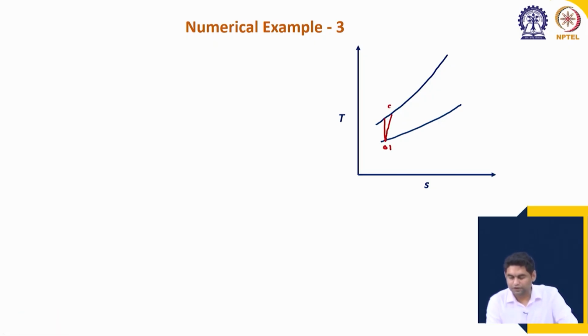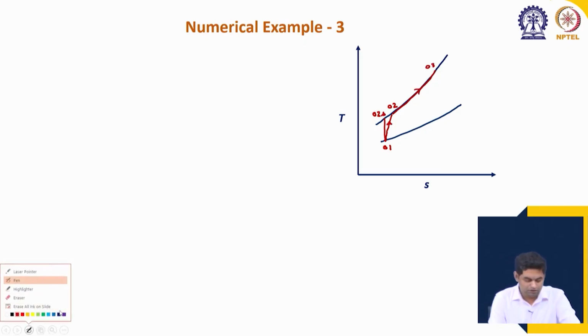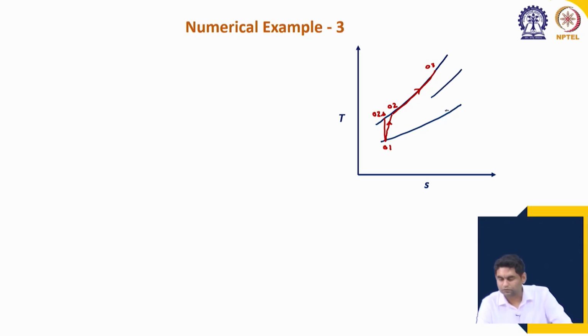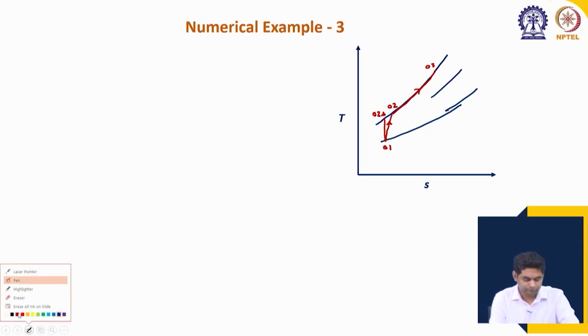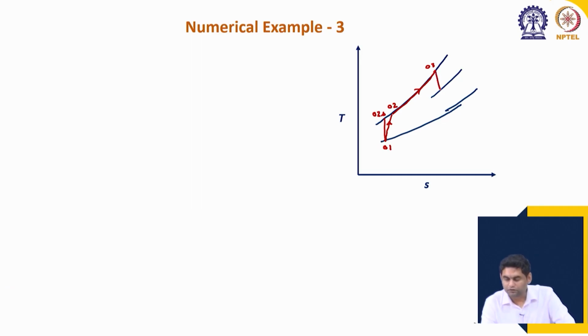So, again you should also practice how to draw these diagrams quickly, because it is very much essential. 01 to 02 compression, 02 to 03 combustion, then 03 to 04 high pressure turbine expansion, 04 to 05 low pressure or free turbine expansion. Okay. So, exhaust gas goes out at 05. This is P05, this is P01, this is P04 and this is P03 equal to P02.